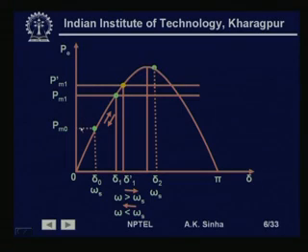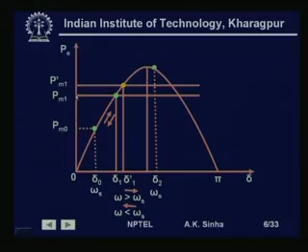Now, we have Pm1 minus Pm0 amount of mechanical input, which is now excess because the electrical output at this instant t is equal to 0 plus is still equal to Pe, which is Pm equal to Pm0, and suddenly we have changed the mechanical input to this value. So, this is the amount of accelerating power which will be available with us, because this is the excess mechanical power available to the system.